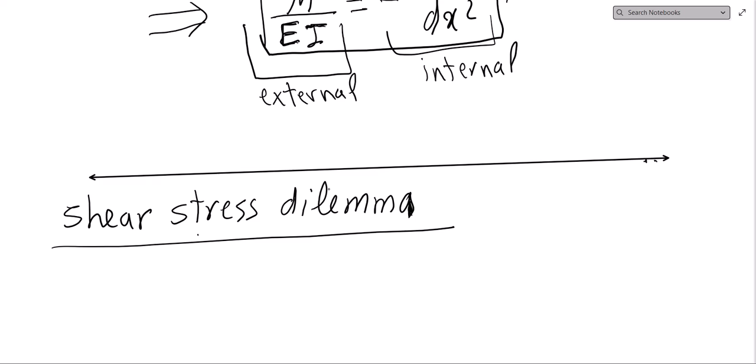In other words, we can say that Euler beam theory, based on the two major assumptions that we discussed, decouples the stress due to bending and the stress due to shear. These two are calculated separately. They don't connect to each other. Bending stress is a direct consequence of kinematics and of course kinetics of the beam, and shear stress has to be recovered based on the equilibrium.